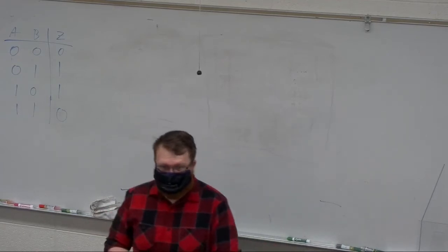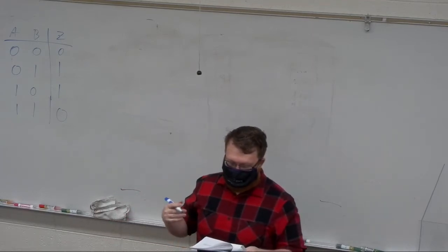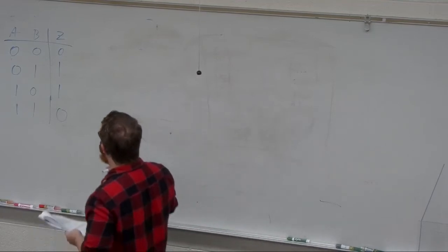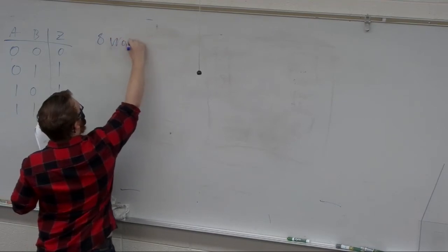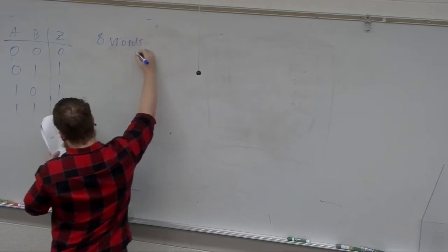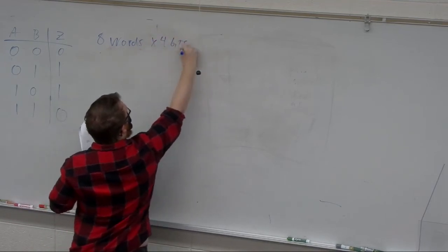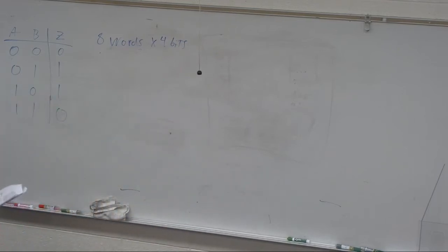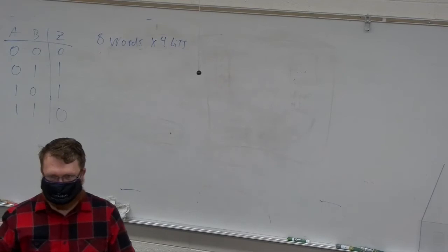And that's all a ROM is, a series of what we call lookup tables, LUTs. And you'll see them defined as something like it'll have 8 words by 4 bits. And that's how they'll describe how big this memory has to be. And so you can look at how large your ROM has to be, because there's no tricks, there's nothing clever going on about it. It's just straightforward lookup tables.